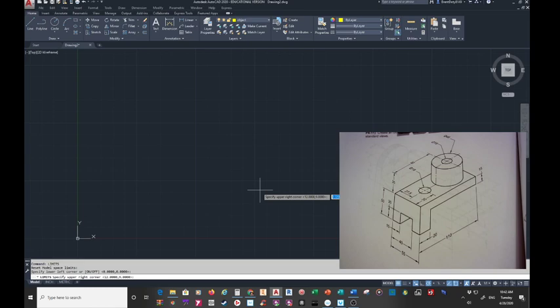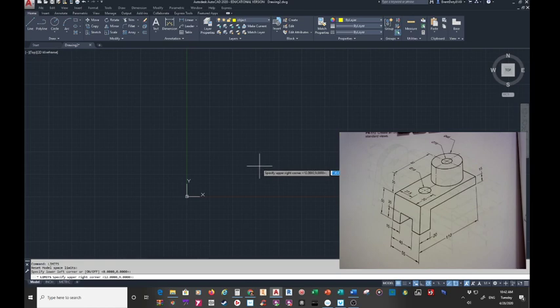Now you're thinking, well, you just zoom out. Well, yes and no. The way our zoom works, whenever you use your scroll button in and out, it is looking at your limits as an idea of how much area it can zoom in and out of, easily. And for some reason, if you don't set your limits up, and it doesn't have to be exact, but if you don't adjust your limits, your zoom can end up being goofy and not working right and frustrating, which is something that we don't need.